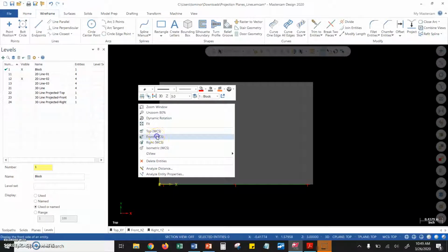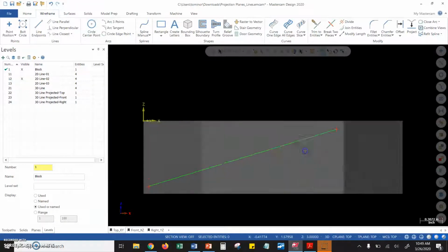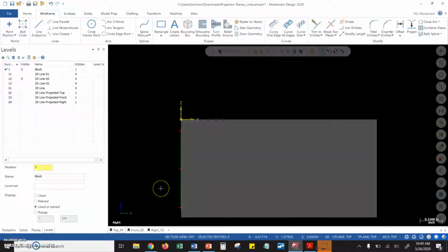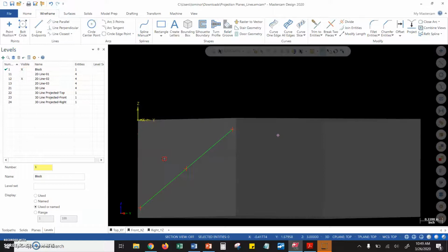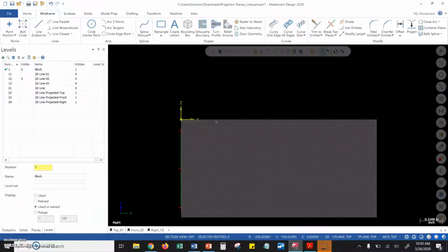We'll switch over to the front view, and now we can see, this tells more of the story. Line number 2 is actually drawn at an angle. Looking from the right view, interestingly, we see a line with number 2, whereas with line number 1 from the right view, all we saw was a point. Well, that makes sense because this line is drawn on a diagonal, so if you only look at it from the right view, you see its length along the z-axis only.